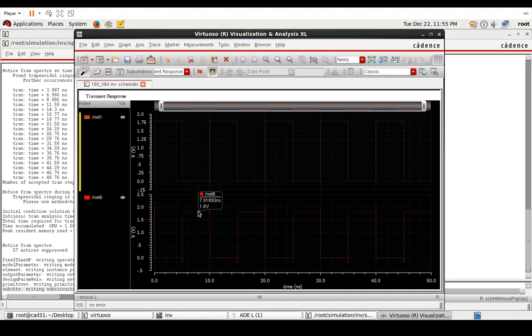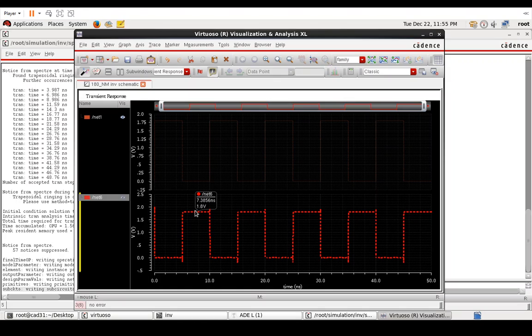Okay, we are designing what are called static CMOS circuits, which means that the voltage levels at steady state of operation, meaning that the input is constant in this duration, the output should be at a perfect value of 1.8 or 0. That depends on the functionality, but it cannot be at any other intermediate values. Okay, which means that something is wrong with the connection.